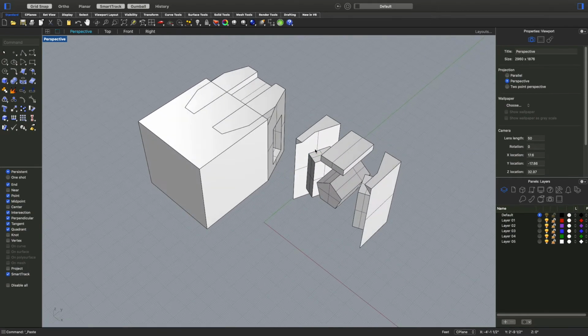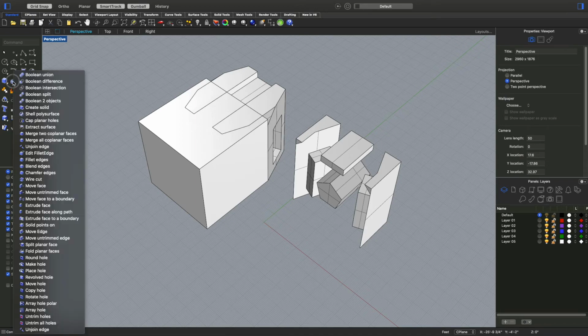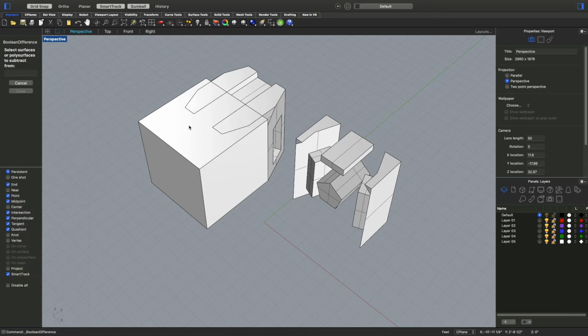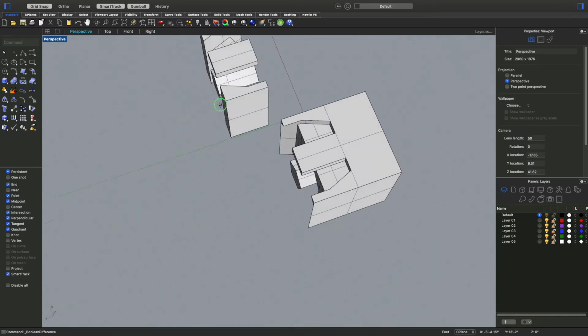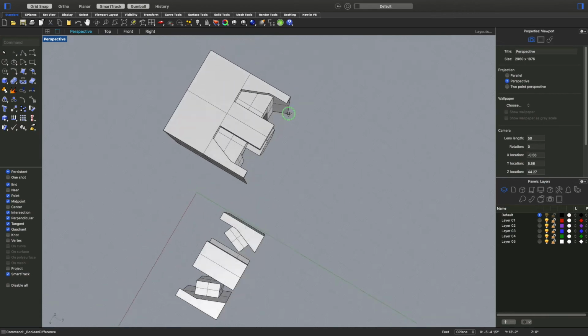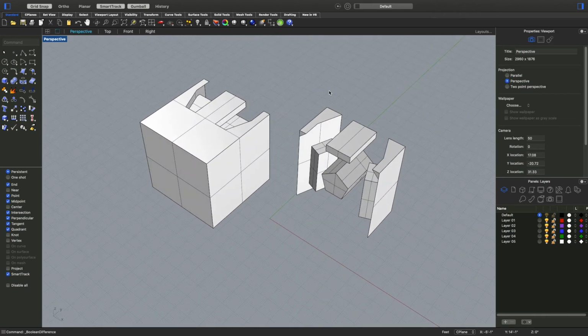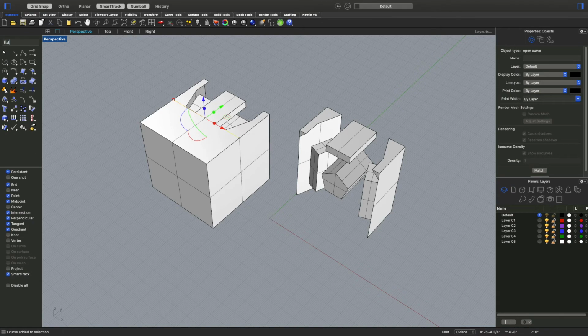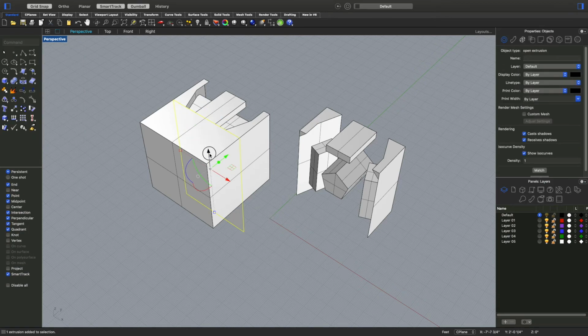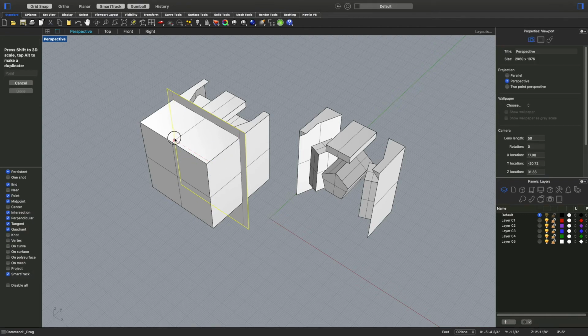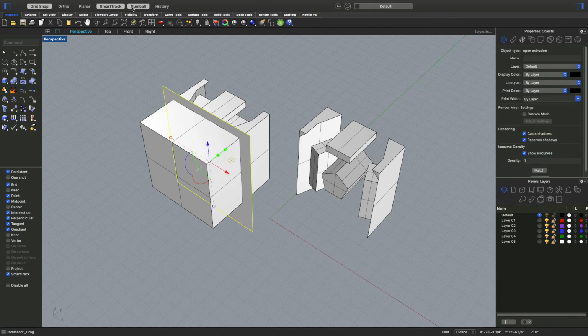Now we're making the other one. So let's Boolean difference again. Boolean difference. Want to keep this, enter, and get rid of this, enter. And we've got the other negative space. So now we're just going to repeat that same step again. Draw the line from this point to this point. Click on the curve, extrude curve, enter. Goes through, click on the surface, move it up, scale it out with the gumball. Gumball's turned on up here, otherwise you can't see that.